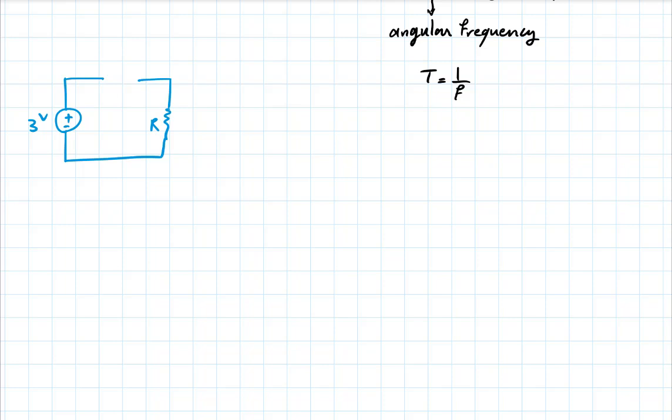Now, what is the voltage drop across the diode? Imagine there's still this diode here. I've removed it because I want to remind us that there is no current. But what is the voltage drop across the diode in this case? What is V? 3 volts, right? Because there is no current, so there's no voltage drop across R. The entire 3 volts are appearing across the diode in the forward direction, right? Which is not consistent with the assumption that the diode is off. Okay? So this is sort of the most basic diode circuit, if you want.